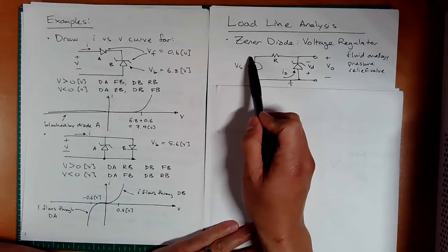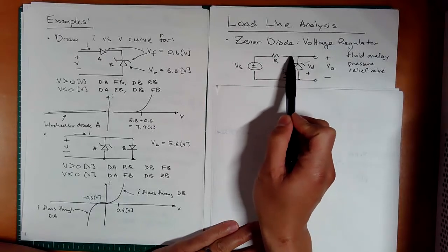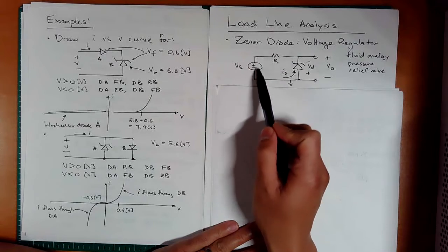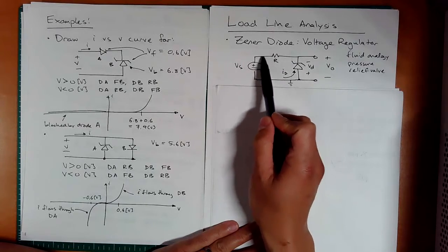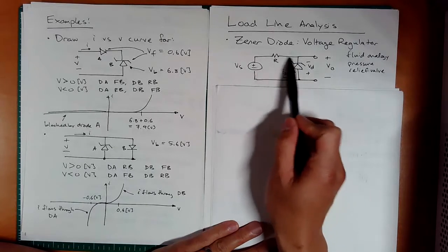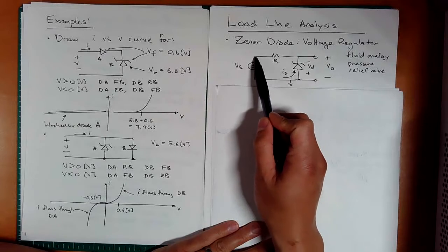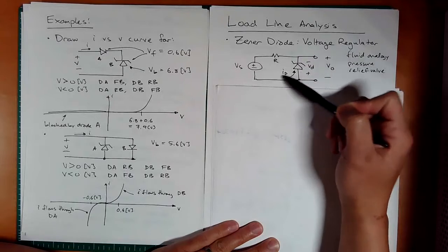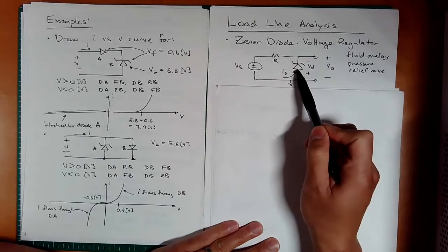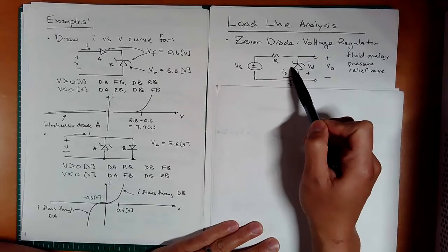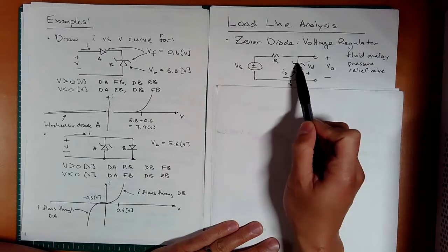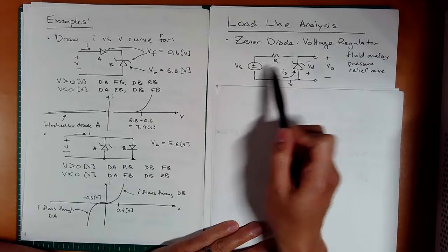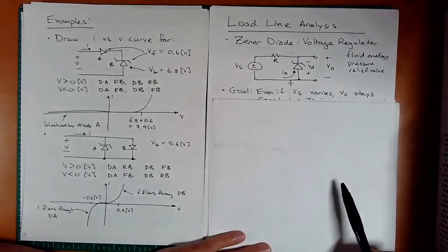This is going to want current to go through, right? And then, or sorry, if this starts at 0 volts, this is going to be blocked. No current's going to flow at all. But as I increase, eventually, once this surpasses the back voltage, this is just going to allow current to flow through here and not allow the pressure on this side to build up. Okay, and so this will maintain whatever back voltage is designed into this Zener diode, and this one can kind of vary up and down.